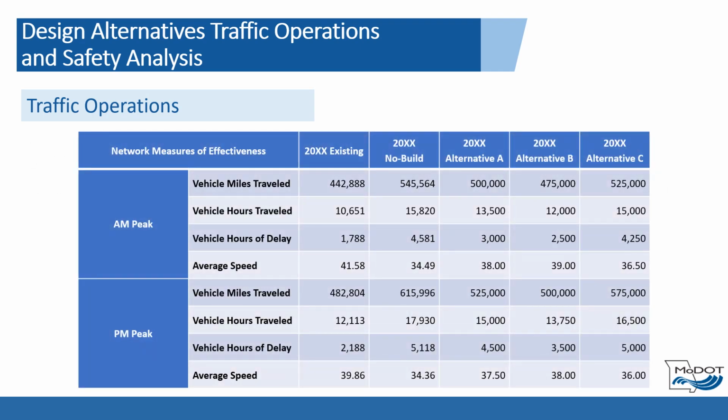If several MOEs are being considered, a table like the one displayed may be helpful in communicating the MOEs for each scenario. If a single MOE is being considered, figures specific to that MOE may be more useful in comparing traffic conditions for each scenario. An example can be used to compare MOEs between different scenarios.